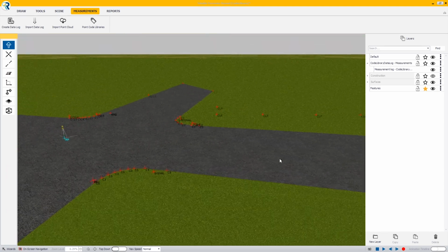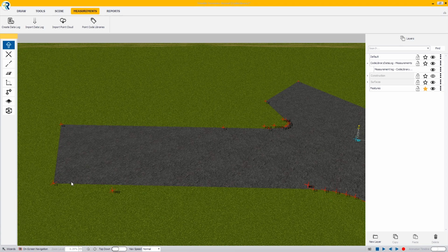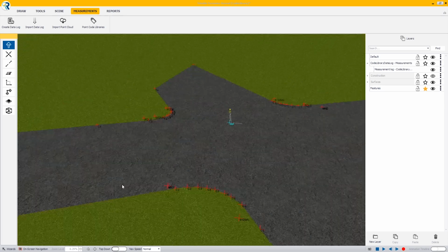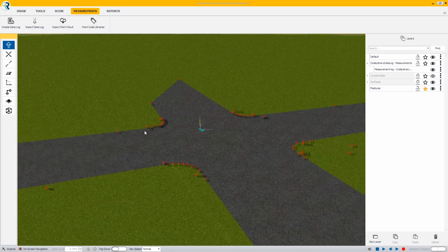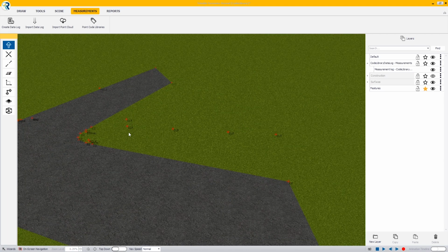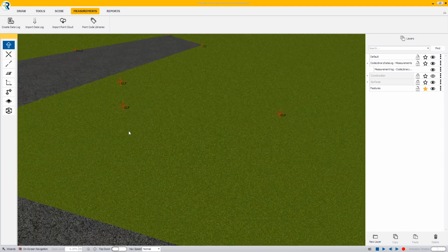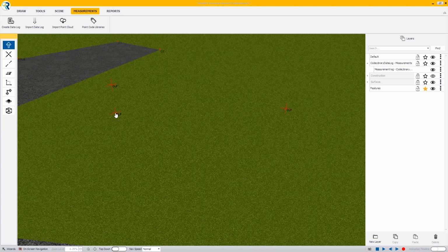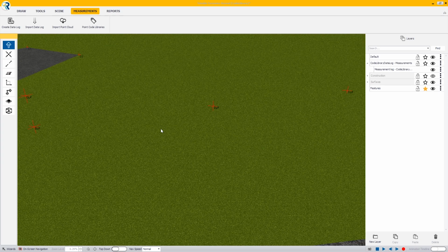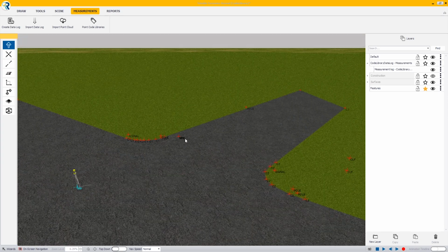So now we have our scene here, and I could go through and I could draw all of these things manually, but that takes time. And I know when I go out and shoot my scenes, if I have 4 curbs, I've got C1, C2, C3, and C4, and I always code that the same every time. The same thing with my chain link fence. So here I shot the bottom of my fence and then the top rail, and then I used the prism pole to walk down through and got 4 more points along my chain link fence. For my manhole cover, I used the prism pole to shoot the center of the manhole cover, and that is where the manhole cover was, or at least the center of it.